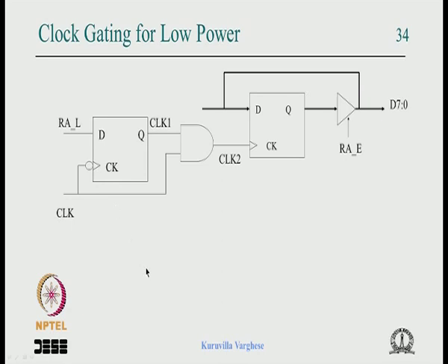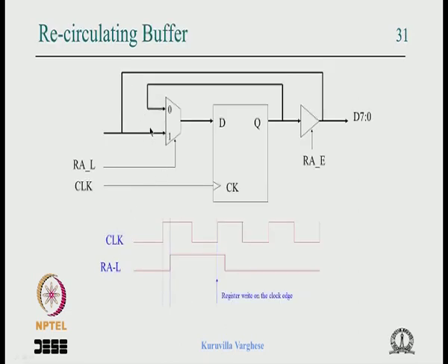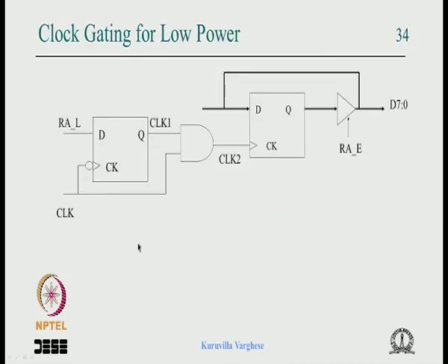Even if you implement with a recirculating buffer, the tools detect that it is a clock gate kind of recirculating buffer, and can do the proper clock gating by replacing that with this, because it's very regular, and it has to be very close to the real flip flop.